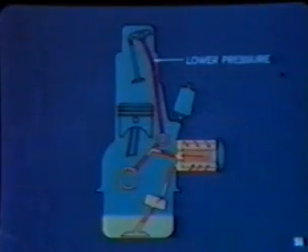Beyond the main gallery, pressure is reduced by restricting the size of the passages. The valve train parts, other than the lifters, generally receive a lower pressure oil feed. And as the oil drips back to the oil pan, it lubricates the parts that are not pressure fed or lubricated by oil mist from the crankcase.